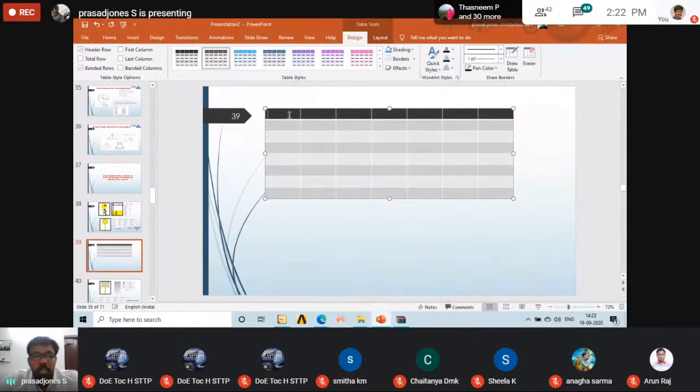Right. So for designing this window, we have to give 6 values for designing the ground or designing any part of the antenna. First is x minimum, the next one is x maximum, and next one is y minimum, and next one is y maximum, the next one is z minimum, and next one is z maximum. Right. So these are the 6 values in order to design any part of the antenna.